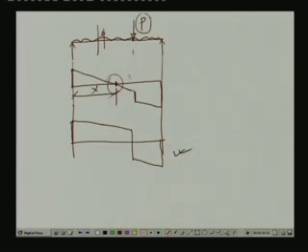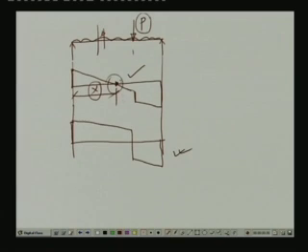Now, if we consider this particular case, that at a distance X somewhere the shear force equals 0, we are trying to find a point where shear force is 0 because at that particular point we know that the bending moment will be maximum. So, the bending moment could be maximum where the shear force is equal to 0, or it could be maximum where there is a changeover from positive to negative or negative to positive sign. Now, we have these two possible cases in this particular case.